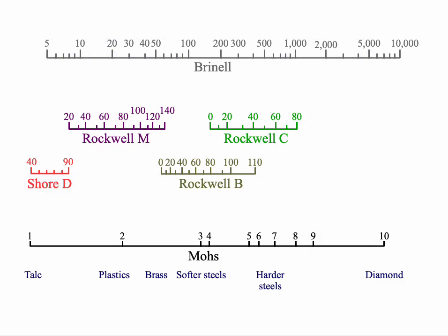One of the reasons we check hardness of a metal part is so we can compare it with specifications to see if it's what we paid for. So if you check hardness on a Brinell tester, but the specification is in Rockwell B, then you've got a problem. Fortunately, all the major hardness testing companies publish posters with conversion tables.